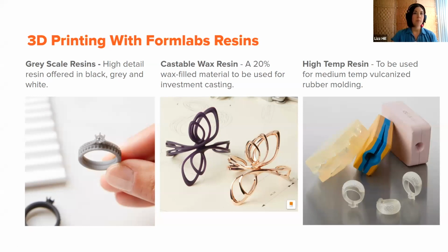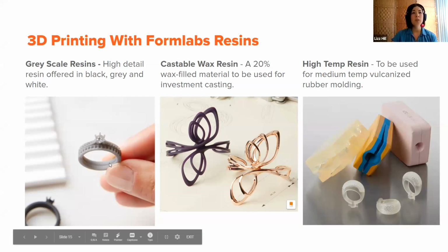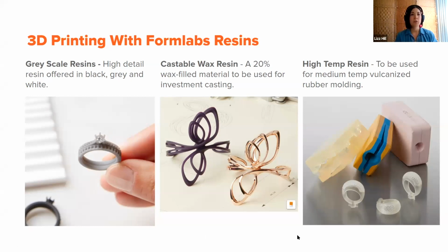If you were prototyping, printing your own designs to review them or to review with a customer for fit, for overall aesthetic, you would likely use gray, maybe white, maybe black. Gray we find is the easiest to read in terms of the small details. You can really see them clearly. And it's our most commonly used resin. As a professional 3D modeler and jewelry designer, I used gray resin very heavily.